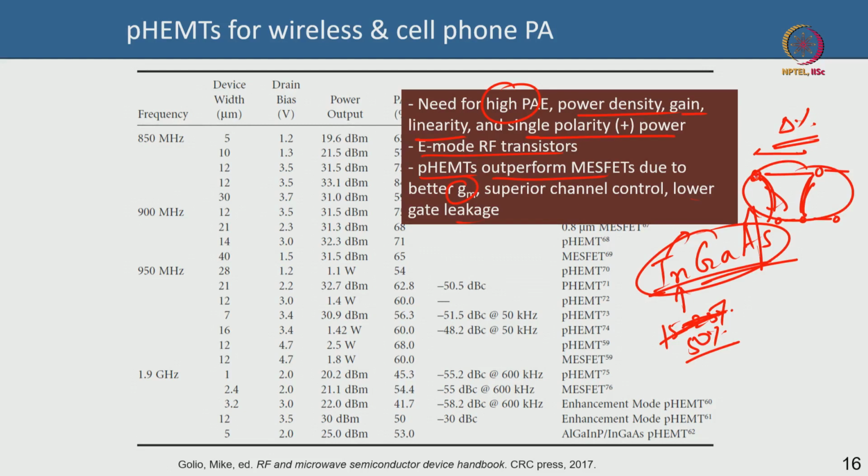So the atoms of indium gallium arsenide will try to go back to their original position instead of being forced to mimic the lattice spacing below. When a material relaxes on top of another material epitaxially, misfit dislocations appear, which means there will be a missing line of atoms. In the same span you have so many gallium arsenide spacings, but only 2 or 1 indium gallium arsenide spacing, and you are forcing them otherwise, but once it relaxes you will have a missing line of atoms because of this, and those are dislocations that are not good for devices.